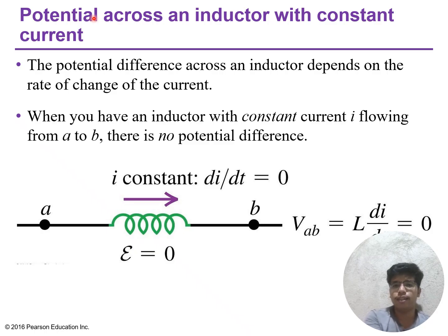Inductors store energy rather than dissipate it. Power in a steady current inductor is P is equal to V sub L times I is equal to 0 times I is equal to 0. While energy stored is U is equal to 1 half L i squared, initially the inductor resists current rise. So V subscript L opposes battery voltage. Then voltage decreases as di over dt decreases. At steady state, di over dt is equal to 0 and V subscript L is equal to 0. The resistor sees V subscript R is equal to IR and the inductor stores constant energy without dissipation.